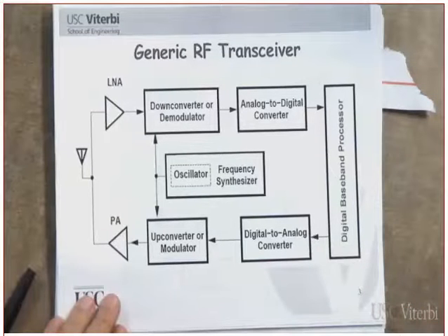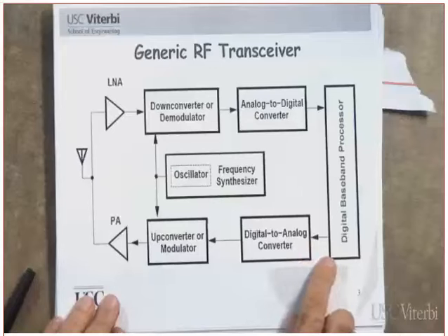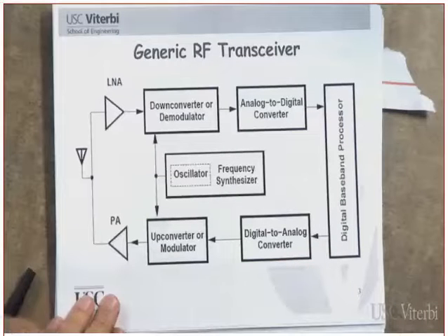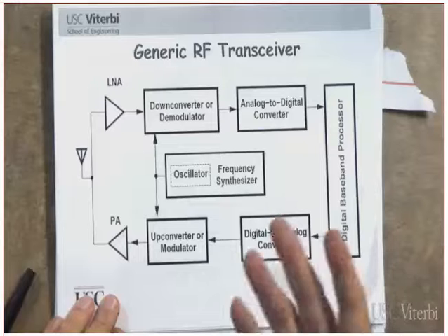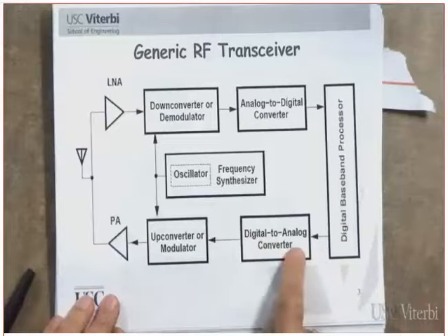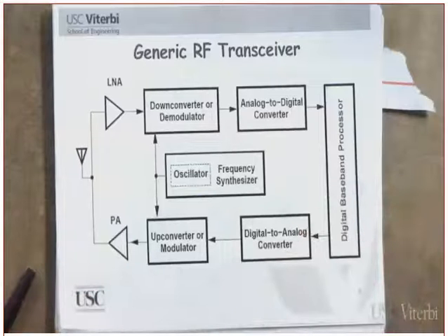An up converter or a modulator is a device that will shift the spectrum from around 0, which is the baseband, to around the so-called carrier frequency, the RF signal. Now, the first question that we need to answer shortly, in a minute: why can't we transmit the baseband signal as is? Can we radiate the baseband signal as is without modulation?